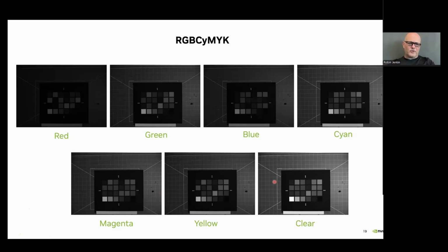One of the reasons that we want to use the real sensor is we get real noise sources with the real pixel, and that gives us some really interesting behavior in low light. We can get the low light behavior nicely. We can get fixed pattern noise nicely. We can look at things like PRNU when we increase the light sources as well.